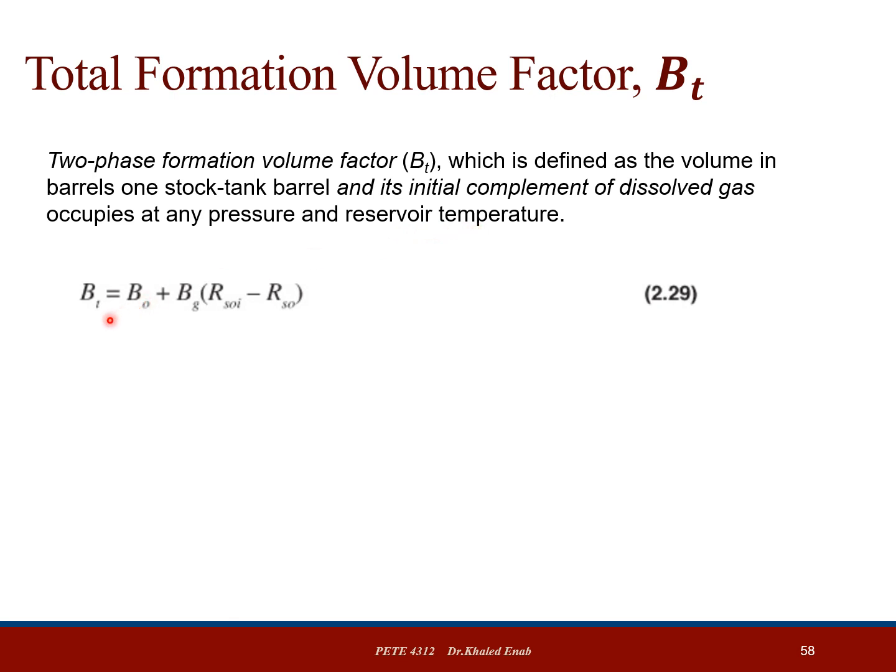The total formation volume factor accounts for the formation volume factor, or the volume of the oil in the reservoir relative to the volume of the oil on the surface, plus the formation volume factor for the gas as well.